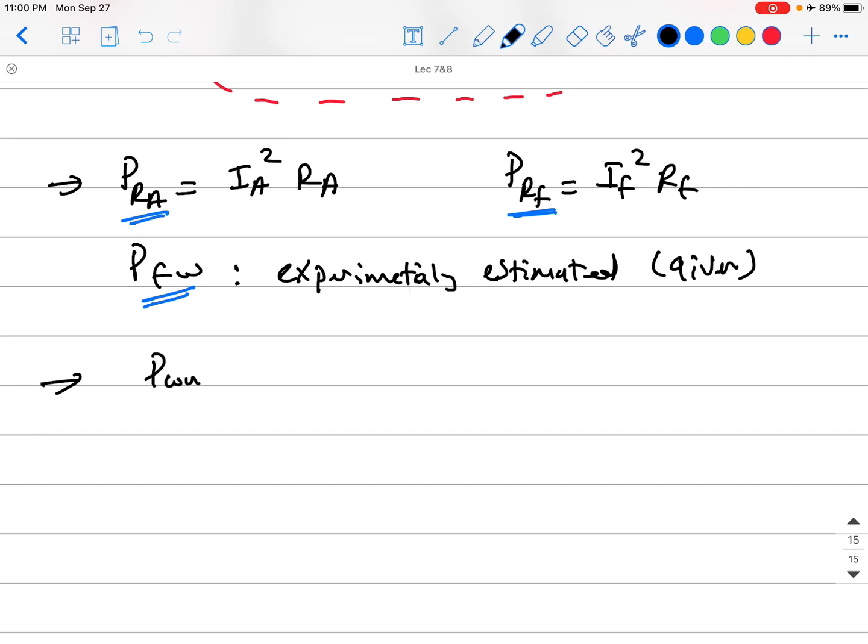For the converted power, it always equals the torque of the motor multiplied by the speed. Okay, guys? And if you substitute for the torque here K phi IA, which is the equation you know, and omega m will be EA divided by K phi.